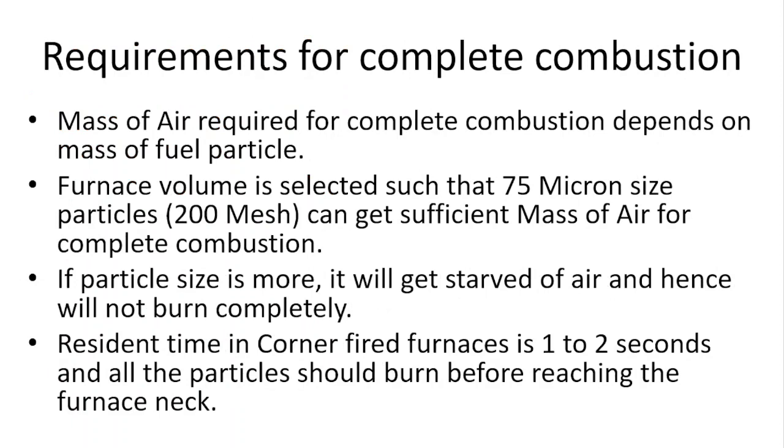The mass of air required for complete combustion depends on the mass of the fuel particle. Furnace volume is selected such that 75 micron size particles, that is 200 mesh, can get sufficient mass of air for complete combustion. If particle size is more, it will get starved of air and hence will not burn completely. Residence time in corner-fired furnaces is from 1 to 2 seconds, and all the particles should burn before reaching the furnace neck.